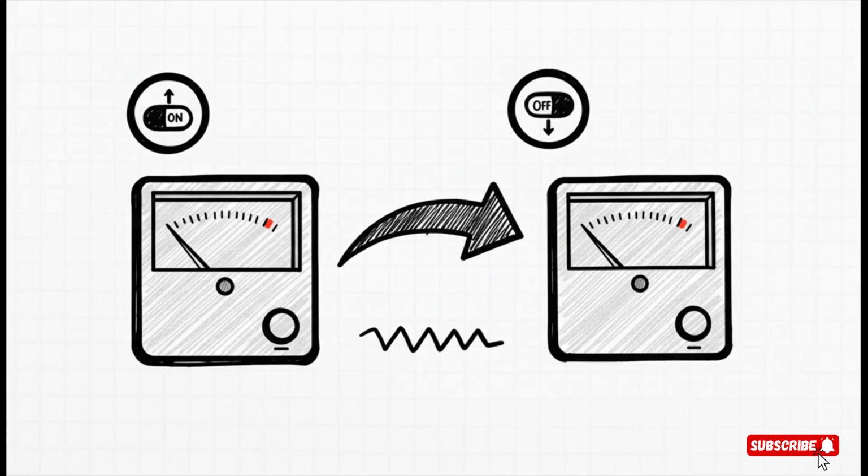Here's another key test. A technician can actually interrupt the CP system for just a second. So you measure the potential with the system running. We call that the on potential. Then you flip a switch, turn it off for a moment, and measure again. That's the off potential. In a healthy system, you should see a big jump between those two readings, at least 100 millivolts. That jump, that potential shift, is your proof that the CP current is actually getting to the pipe and doing its job. If the reading barely budges, that's a huge sign that your current is being short-circuited.